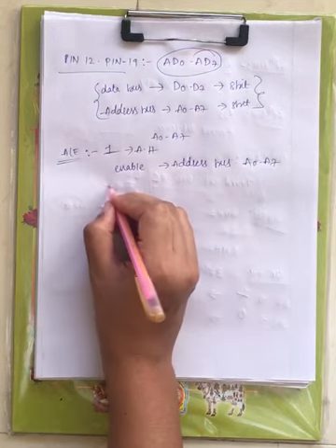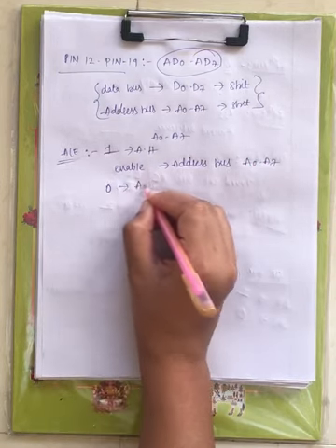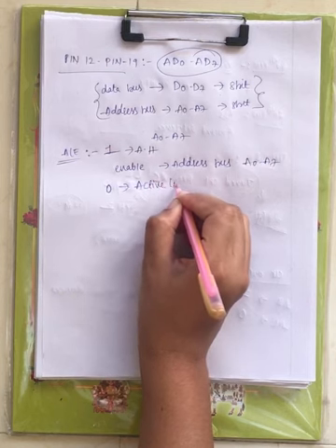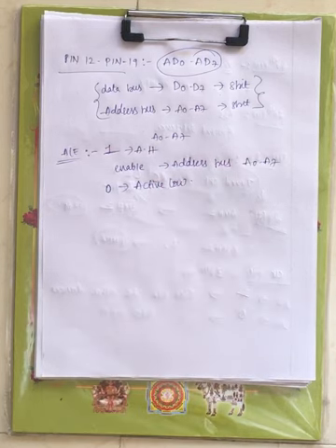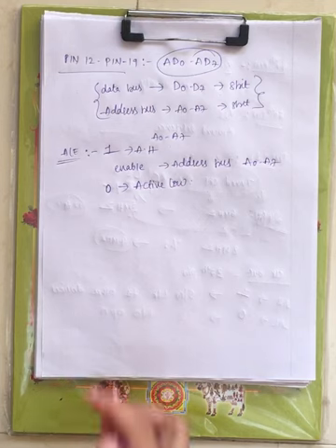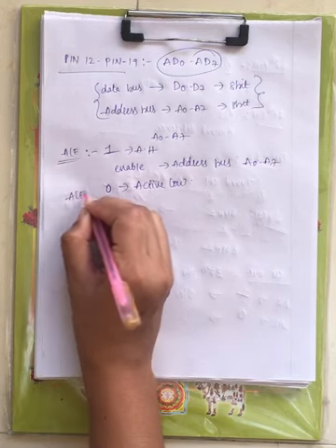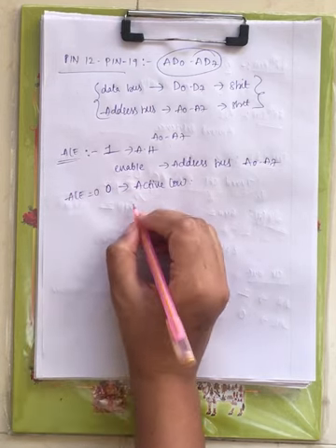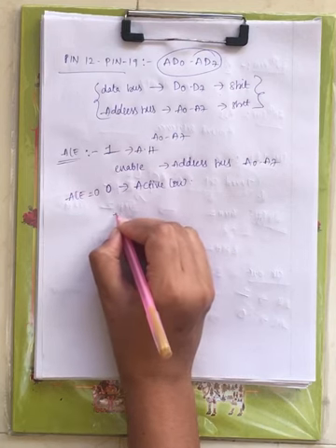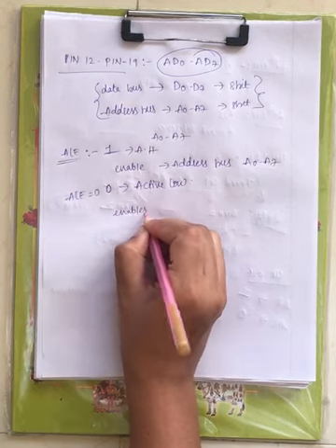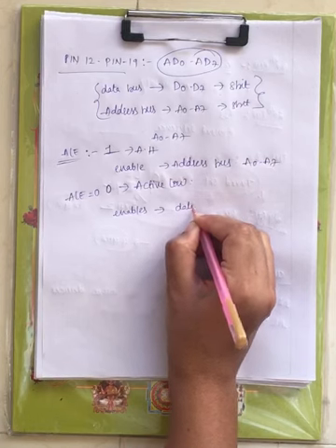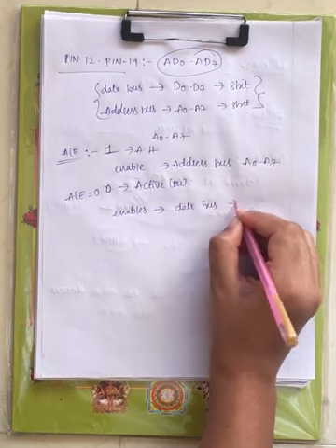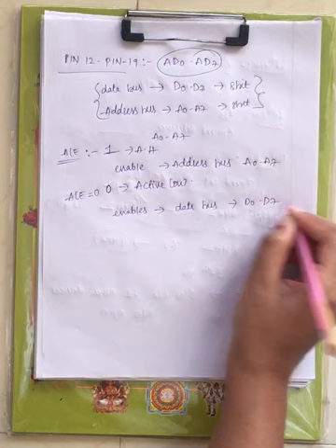When it is 0, which is nothing but active low, you can carry the data bus. It enables the data bus, which will carry D0 to D7.